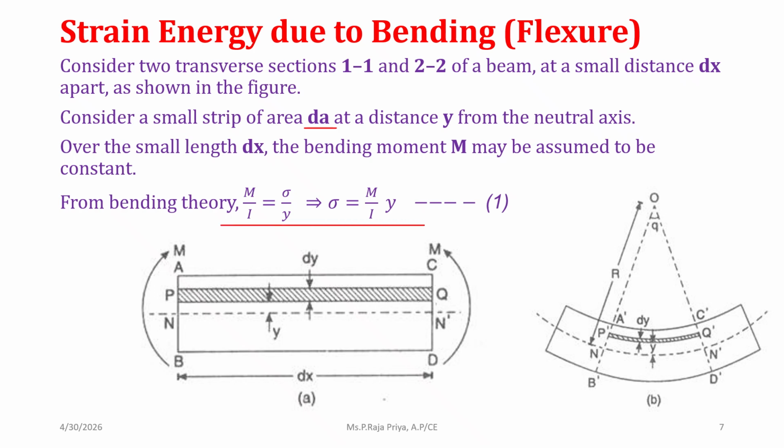This is simple bending theory, which is M by I equal to sigma by y. So from here, taking stress, the stress will be M by I into y. Take this as equation number 1.